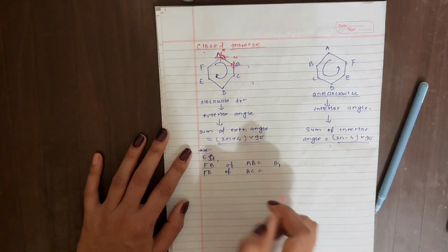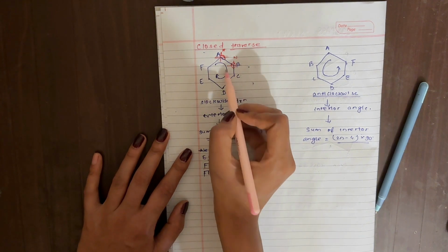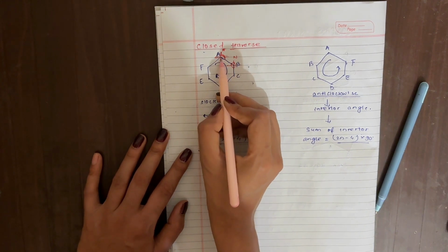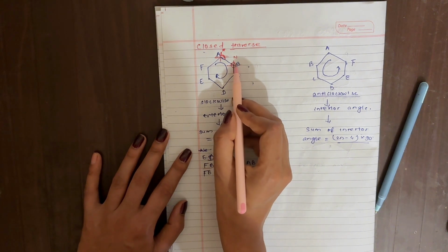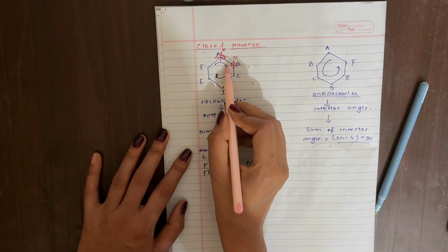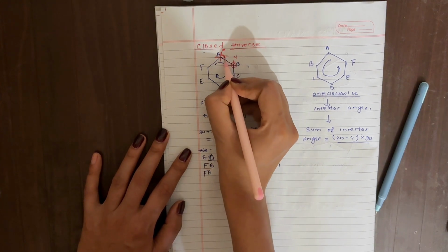Fore bearing is the horizontal angle, in the clockwise direction, which a line makes with the north end of the reference meridian in the direction of progression of the survey line, whereas back bearing is defined as the horizontal angle, in the clockwise direction, which a line makes with the north end of the reference meridian in the direction opposite to the progress of the survey. So this one is the back bearing and this is the fore bearing.